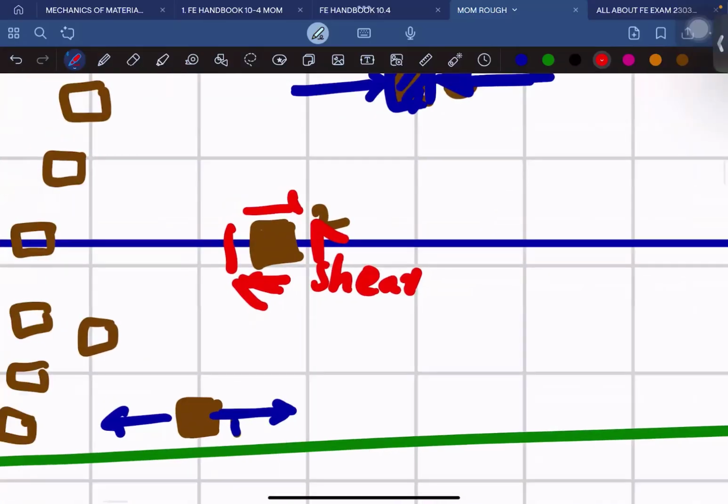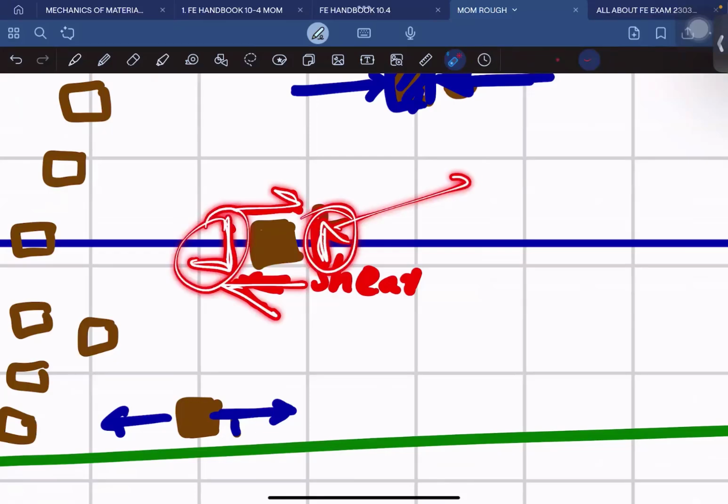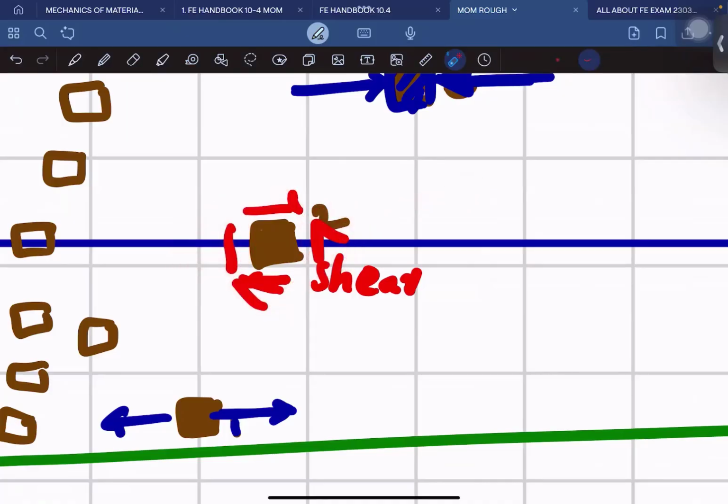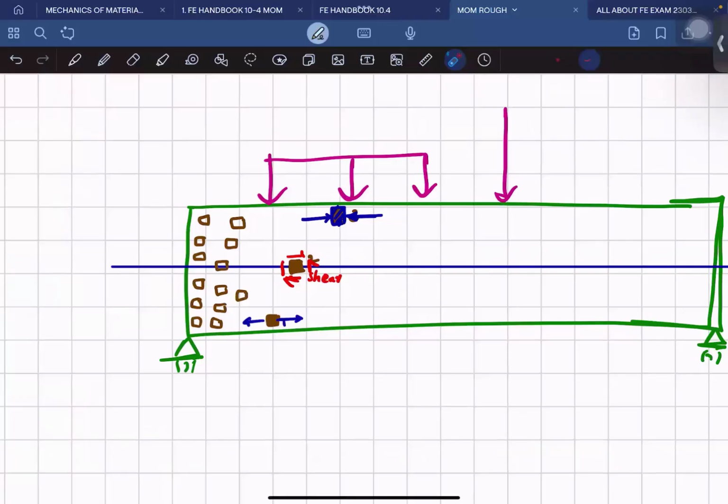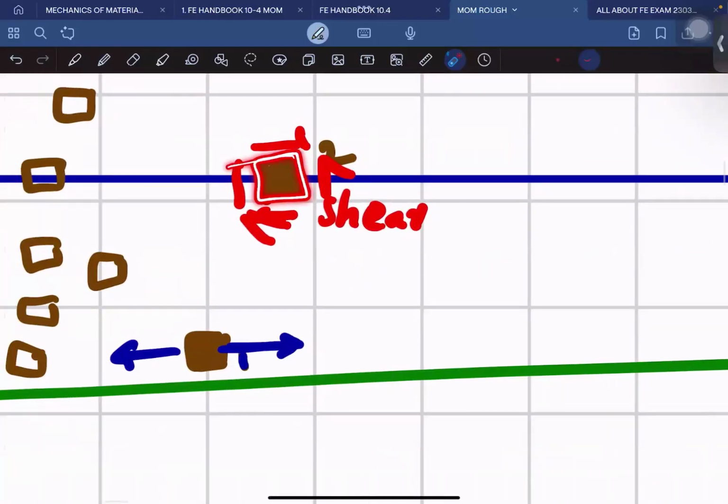And why am I drawing the shear in this direction again, also I have drawn here? There is some reason why there are shear forces acting in this direction. Because of moment equilibrium. Yes, we have to maintain the equilibrium. Since these two shears are causing a movement like this, but this element is part of this beam and this beam is at rest, it is not running away, which means that this element is also at rest, which means that equilibrium is satisfied.